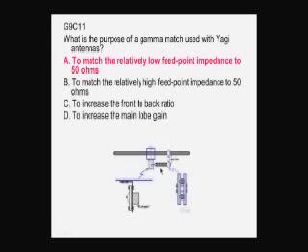And what we have here effectively is a capacitor, because we have a wire here or a rod that goes into an insulating sleeve. There you can see a little bit of the insulating sleeve. And then we have a metal cylinder around it, which is the other pole of the capacitor. And then that is connected to this driven element by this metal shorting bar. Okay? And by adjusting this, you can adjust the relatively low feed point impedance of this driven element to the 50 ohms that you want for your feed line.